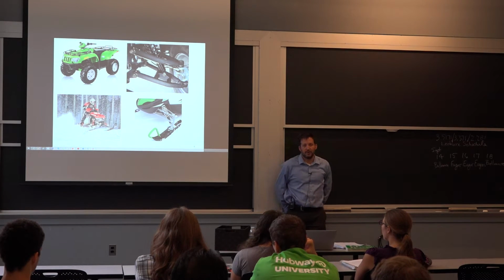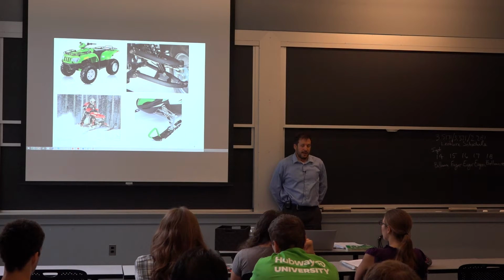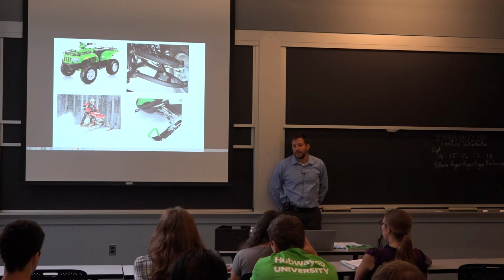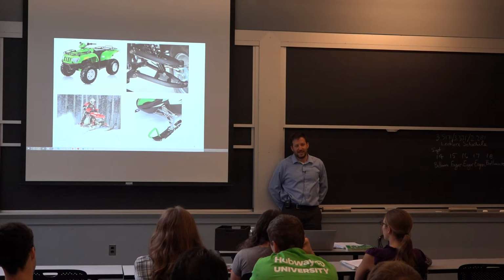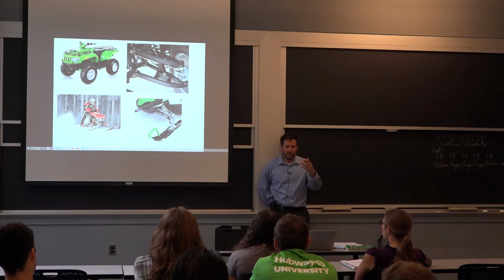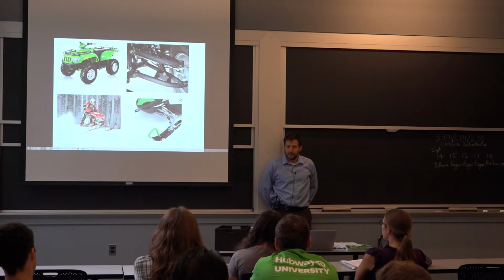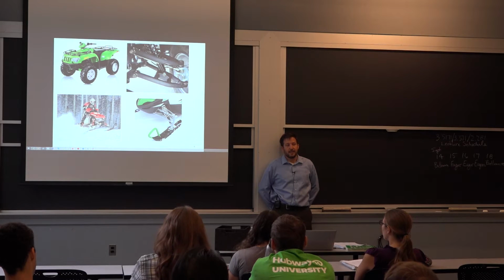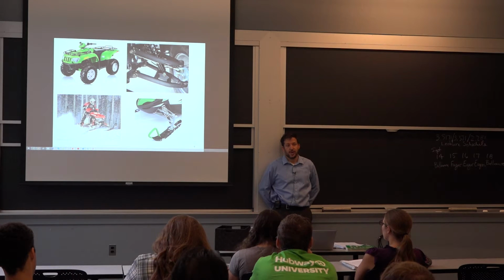And that's a part of failure analysis that is sometimes unfortunate for a manufacturer because it's very hard to prove one way or the other. The only thing that's known for sure is your part broke in two. And when exactly that happened, you don't know. So there is, I guess, a little bit of wisdom here: if you anticipate as an engineer that people will abuse your product and it is a consumer product, it's sometimes much better to let the parts deform as opposed to actually breaking.